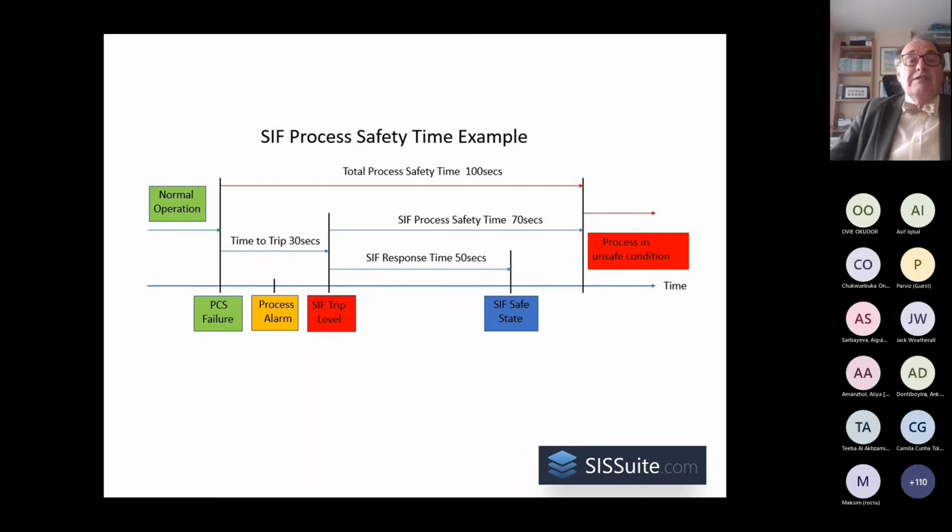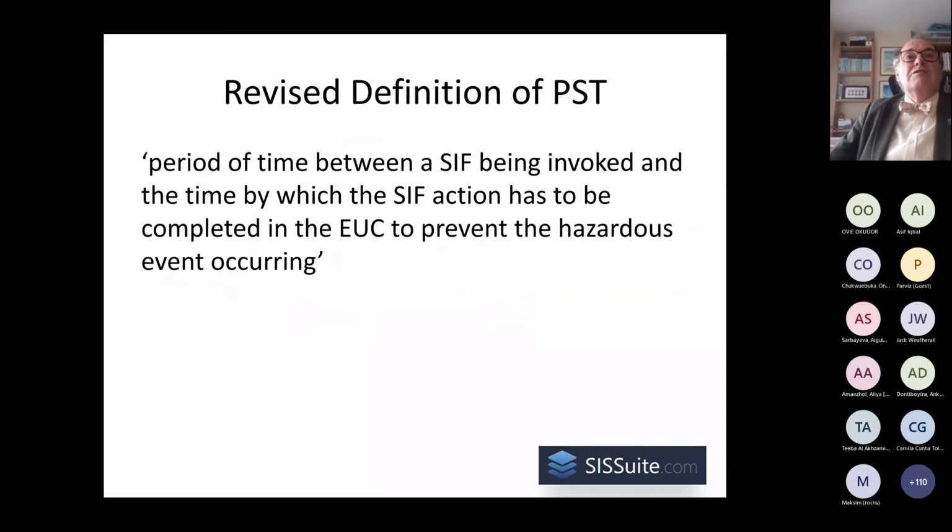In many applications, there is no real difficulty in meeting the response requirements, but there are certainly those applications where it becomes a critical concern. So we do need to consider just what the points to consider are in defining this. So here is my revised definition of process safety time: the period of time between a SIF being invoked, in other words, the trip point, and the time by which the SIF action has to be complete in order to prevent the hazardous event occurring.